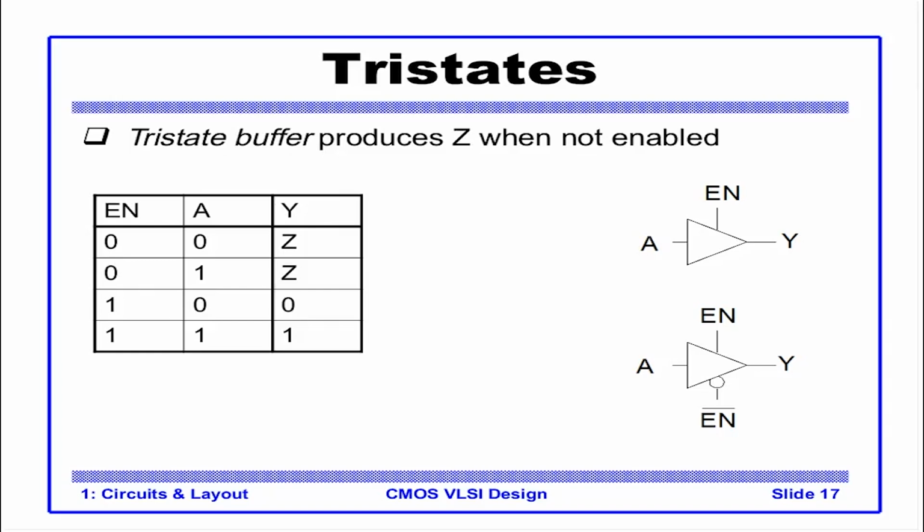Now, in case of transmission gates, the basic gate here is not an inverter but a tri-state buffer, and it has one separate input called the enable pin. It also uses two transistors, but the basic functionality is that of a buffer. However, this also needs the complement of the enable pin, which should also add, let's say, one inverter and two transistors. So the basic gate in case of a transmission gate is a buffer. The basic gate in case of a complementary CMOS is an inverter.